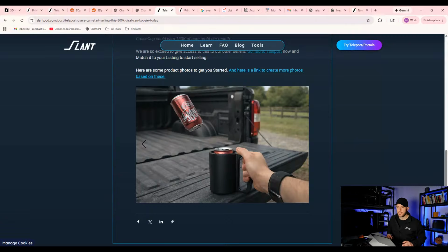Any recommended dimensions to avoid my constant cracking of snap joints? 1 millimeter thick. That gives you flexibility on it. Farouk, go to our YouTube channel, and we have several snap fits and connector videos, and we walk through designing those, and they are all printed and demonstrated in PLA. Because PLA is fast and easy to prototype in. So go ahead and watch those videos, and they go into the detail of it.